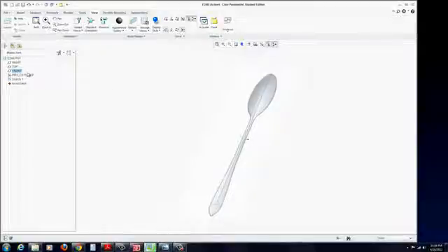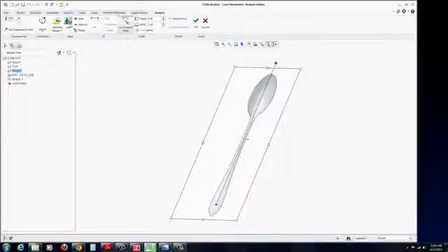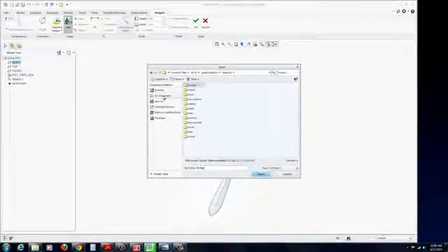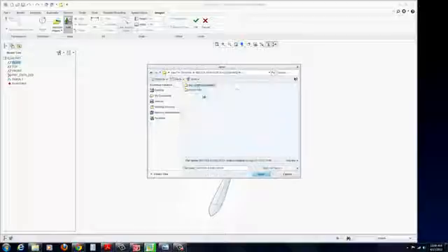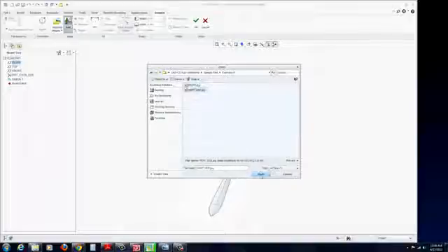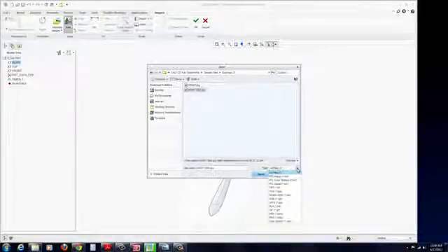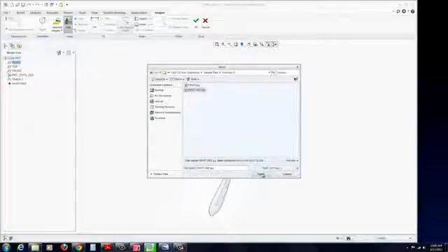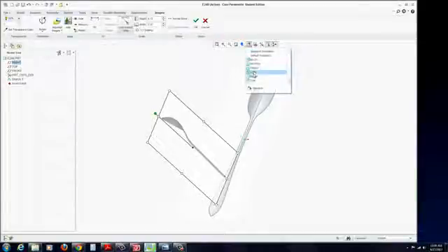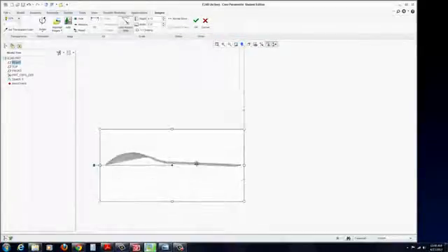Now go ahead and repeat the steps again. Go back to Model Display, Images, click on Add, and this time select the right plane. And we're going to go ahead and find that same file, but this time we want the right side JPEG image. And notice all the types of files that are in here. You could search for TGA, TIFF, bitmap, PNG. Hit open, and we're going to go to the right view orientation and pretty much do the same thing.